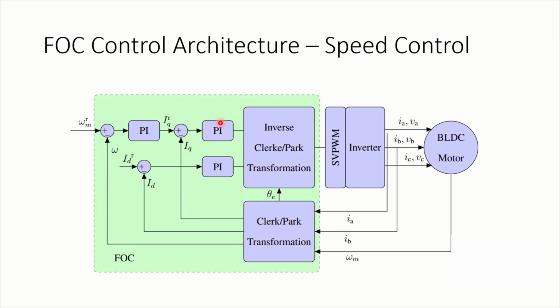So we saw the speed mode control, we saw torque mode control, and we saw the requirement of IQ and why this transformation is required. Because of this transformation, FOC is able to control properly, even though we have a non-linear nature of the voltages and speed.